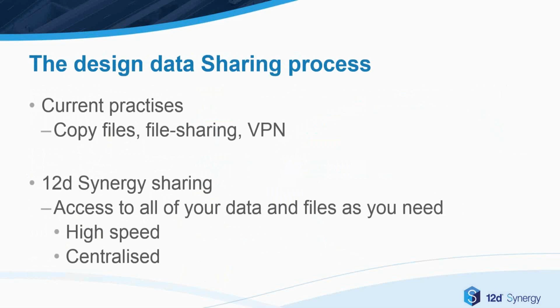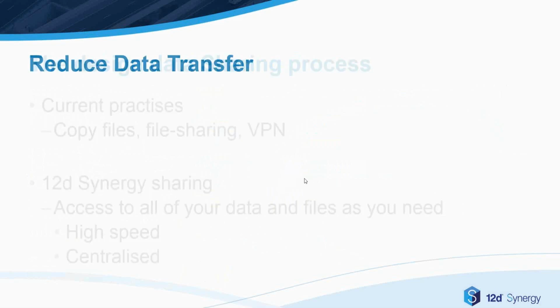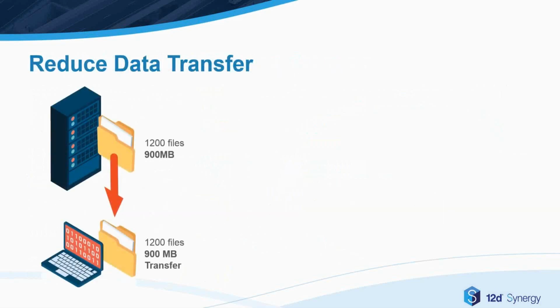And what I'll do now is talk about specifically some of the features that Synergy used to do this. The way we address this is with 12D Synergy's intelligent data transfer. Essentially, you connect to your 12D Synergy server, which could be based in your office or in the cloud. 12D Synergy is a check-in, check-out system, so you will request the files which you want to work on, and they will save to your local workspace.